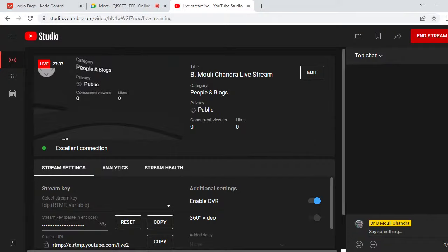Here is the comparative voltage profile we get from the different variants of the PSO algorithm. We consider three different cases: PSO, that is particle swarm optimization, which is the standard one, the modified particle swarm optimization, and the constriction factor particle swarm optimization. These are the comparative voltage profiles when applied to the 33 bus, in case 1 where we have considered 2 DGs and 2 capacitors. From figure 4 A and B, we have observed that the CPSO algorithm gets a better voltage profile as compared to the other two algorithms, that is PSO and MPSO. And these are figure 5 A and B.